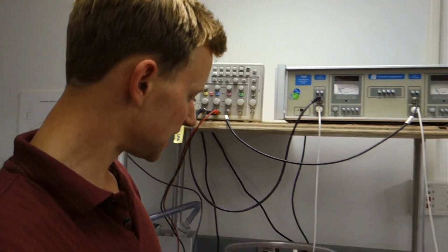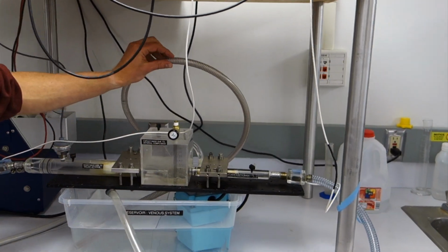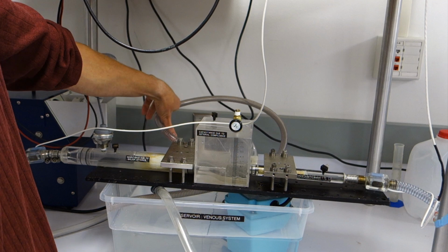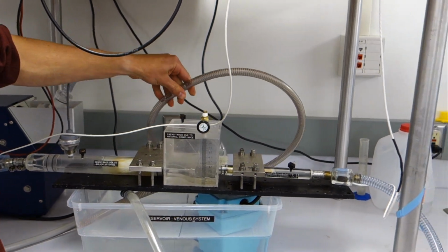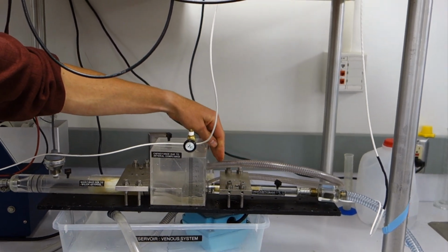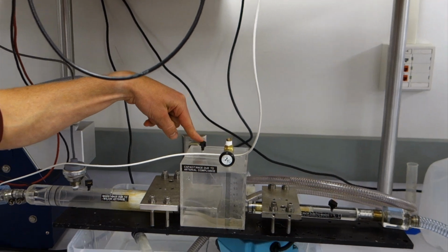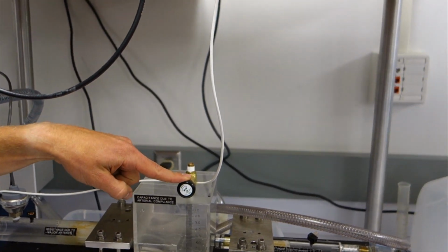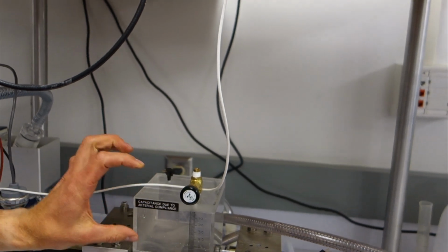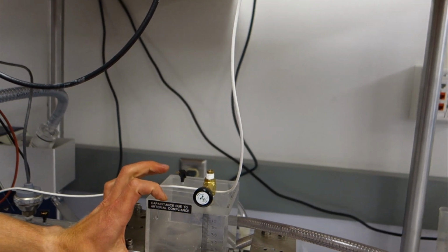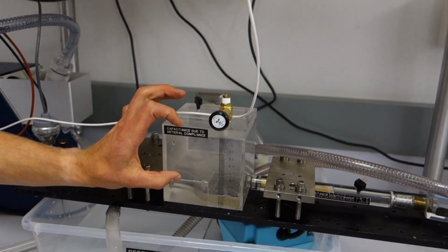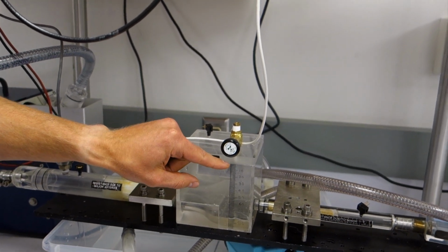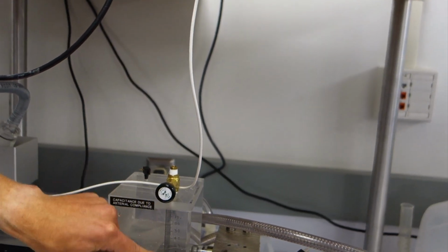Working our way further, we see the box. This is clearly going to be our capacitor. It even says capacitance due to arterial compliance. And it has a few things on it which are worth pointing out. This is a pressure tap which is not hooked up, so we can't use it. This is a valve which we're going to use to change the height of the free surface, to change the amount of air in our capacitor, and hence change the capacitance value. And we're going to measure the capacitance value based on the volume of the air inside of it.